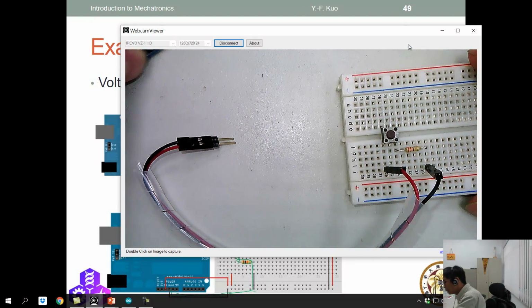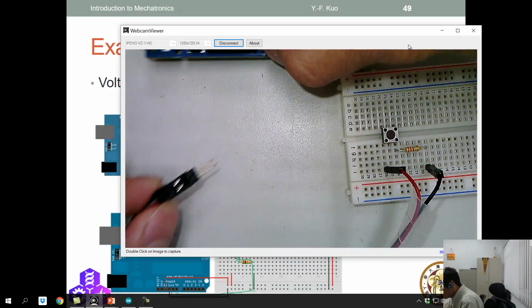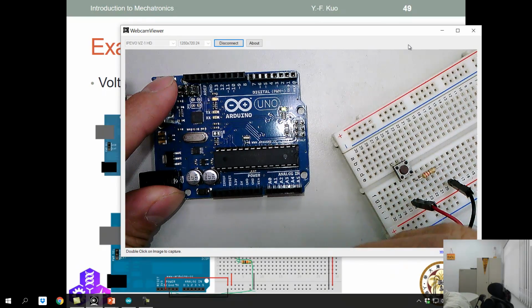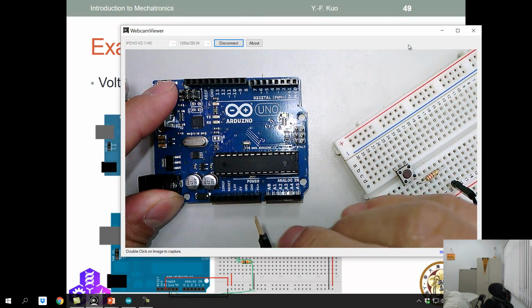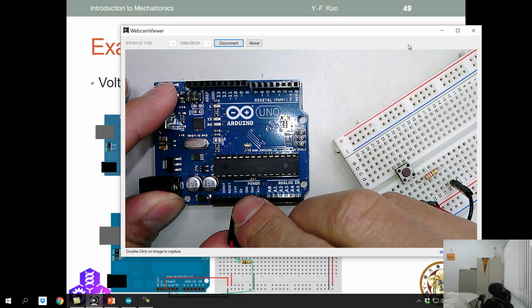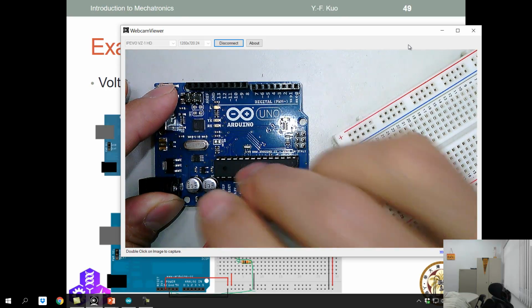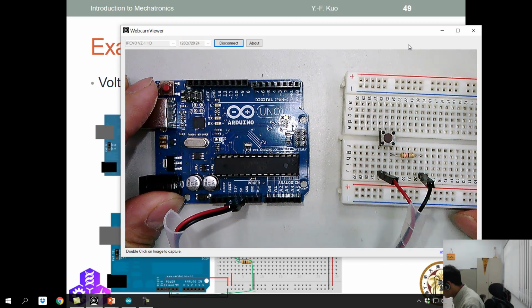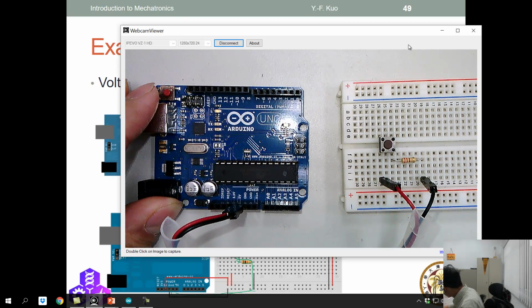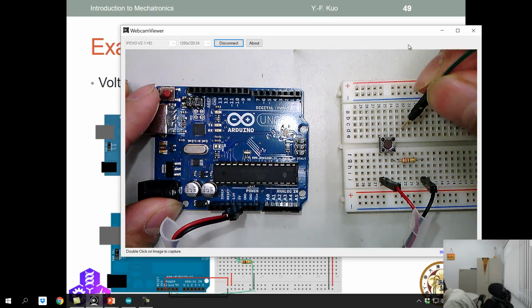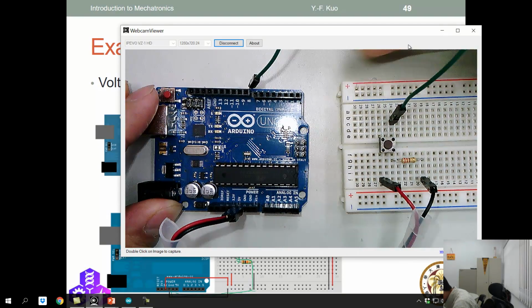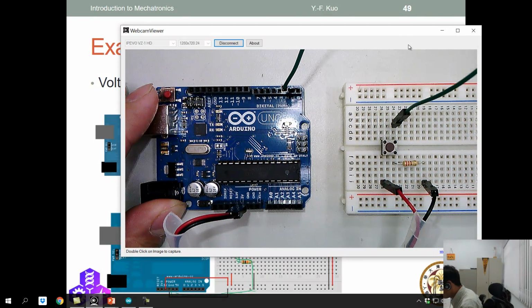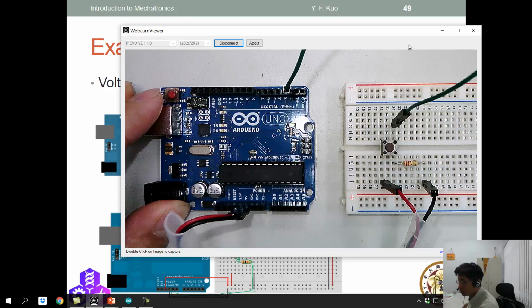Now we want to connect this to Arduino. Now remember, the red line is 5 volts, and the black line is ground. So we connected them together to the Arduino, to the appropriate pins. Okay, it looks like this. Now we have to connect. We need one more wire to connect this button to the pin 2 over here in the Arduino. So this pretty much completes the circuit that we have.